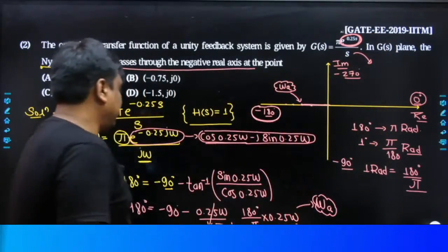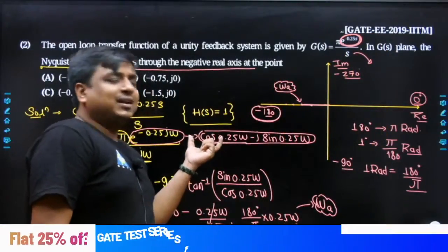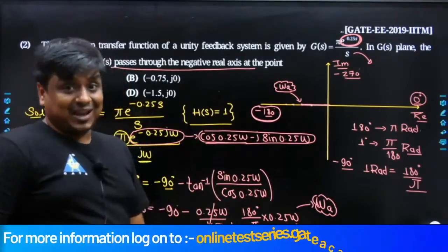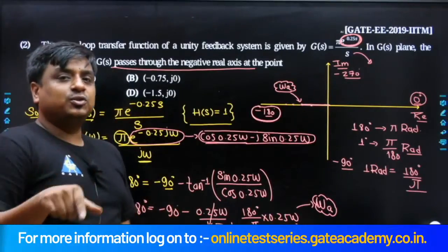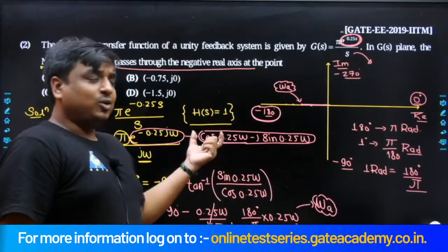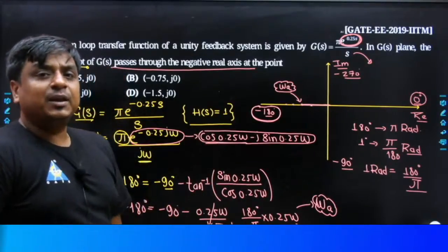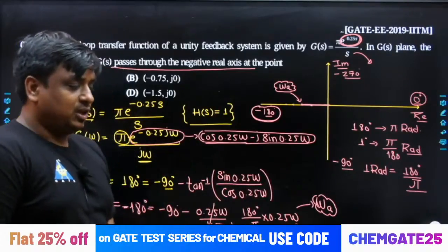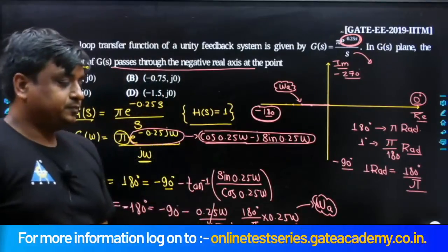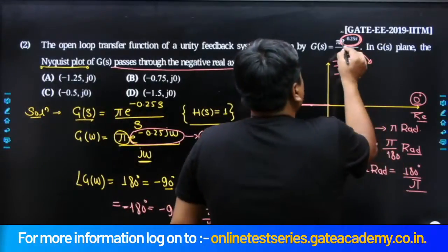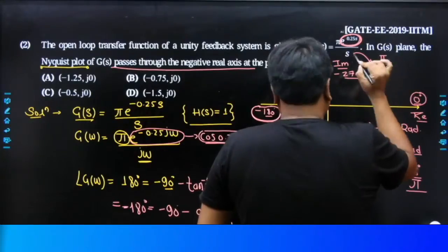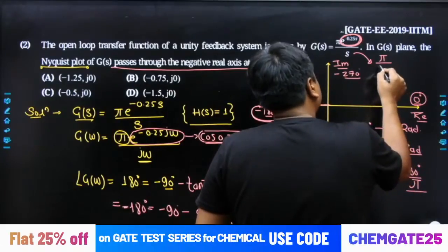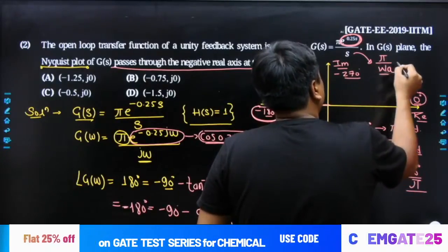Why so? Again the same thing. If we talk about its real part, that is cos of theta, and similarly its imaginary part is minus j sine of theta, and once you take its magnitude, the magnitude is simply going to be the root of its real part, cos square, and similarly imaginary part, sine square. And for all values of theta, the root of cos square theta plus sine square theta would always be 1. Yes, no? So put together, this would not be affected at all, only the magnitude of s has to be taken into account, and once you take the magnitude of s, that is going to be only omega, and we have to calculate that value at omega a.